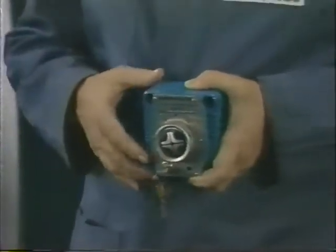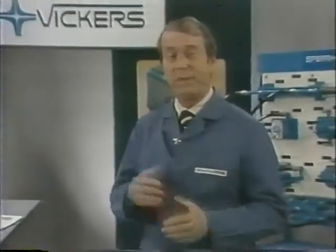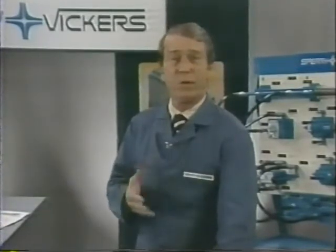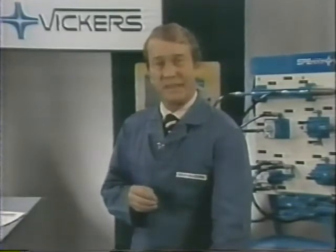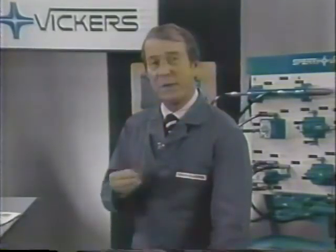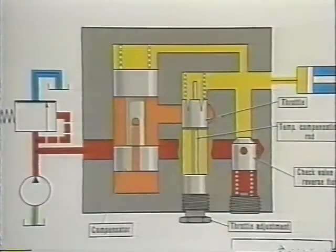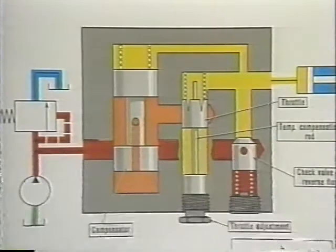Now let's take a look at a flow control that has an additional benefit. We all know that the temperature of oil affects its viscosity. We can get more hot, thin oil through an orifice at a given pressure than we can cold, thick oil. Any change in the temperature of the oil changes its viscosity, which in turn changes the rate of flow through our flow control and the speed of the cylinder. Now here we have a drawing of a pressure-compensated flow control with a temperature-compensating throttle. Its operation is essentially the same as the previous valve.